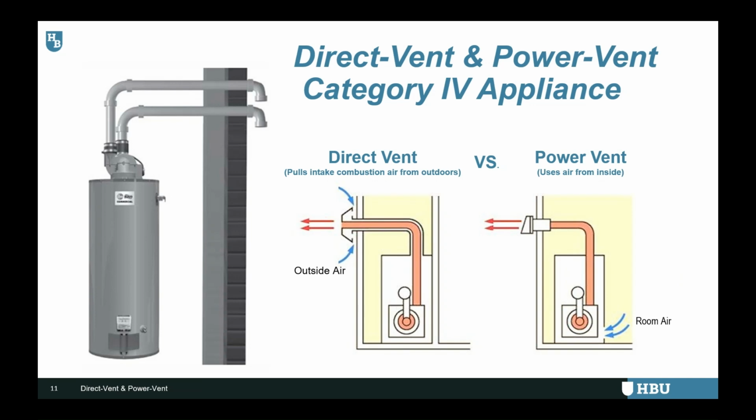In contrast, power direct vent systems utilize a sealed combustion process, drawing all their air from outside and venting directly outdoors. This design, along with the balanced draft and cooler exhaust plume, significantly reduces the risk of indoor spillage and allows for those much closer clearances, sometimes as little as 12 inches from openings.